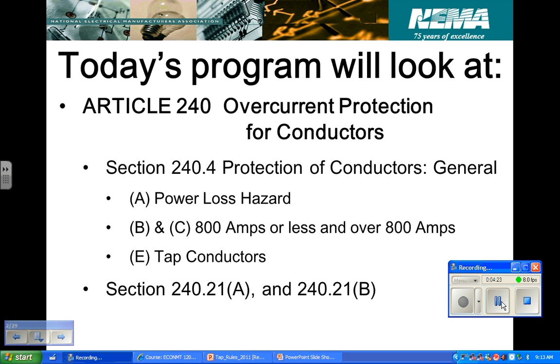Short circuits are dangerous for about less than a quarter of a wave. A quarter of a wave is one quarter of 1/60th, so 4 times 60 is 240. A very big current can flow for about 1/240th of a second. It's a big splash in the water, as it were, because we kind of identify water and electron movement as the same thing. It's like a big blurb of water flying out of a fire hose for just a split second, right? That could probably do some damage, but nothing like that constant flow from a ground fault.